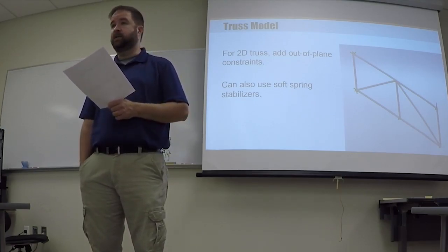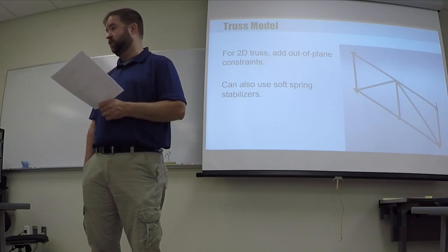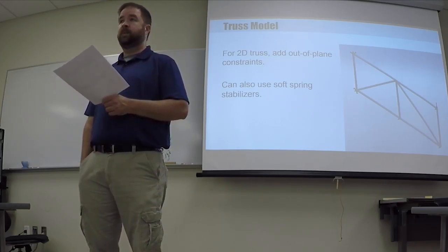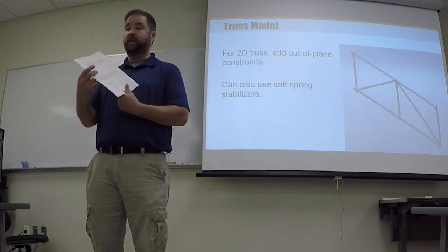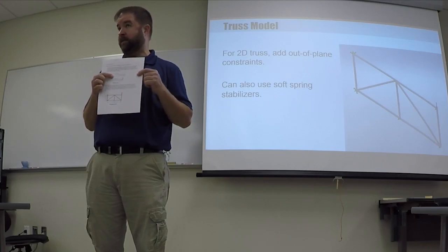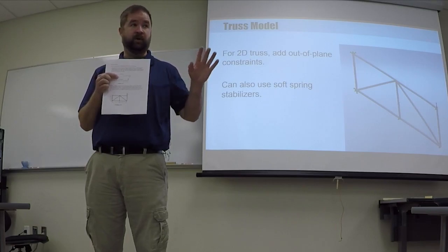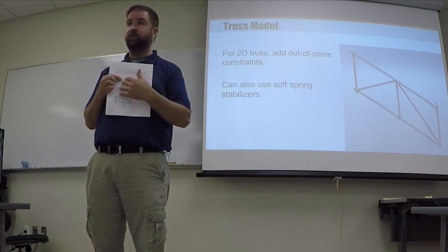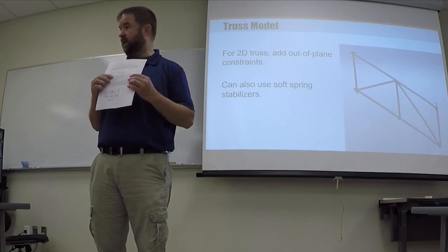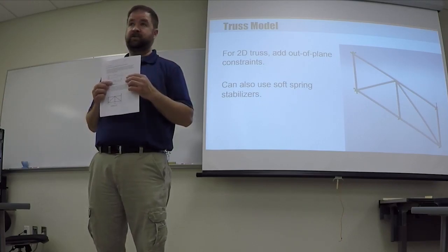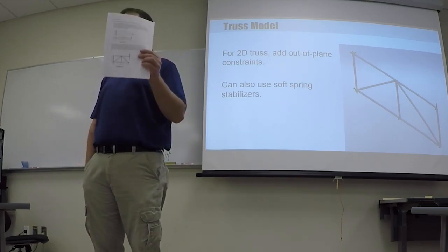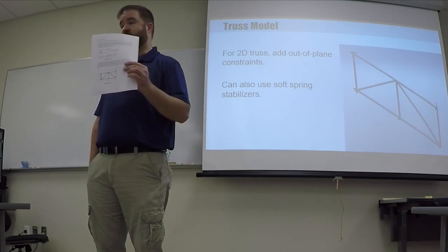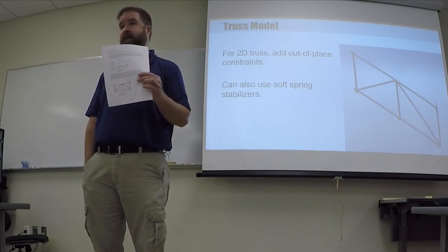The other thing that I need to show you is the way that SolidWorks does beam elements. Everybody listen to me. Do not draw a 3D solid model of a tapered beam in SolidWorks. We'll do that later. This is where I'm artificially forcing you to do it a really simple way. And so your model of this beam is just a single straight line in SolidWorks. So the solid modeling part of this will take you exactly like 10 seconds. Okay, do not draw a tapered beam.